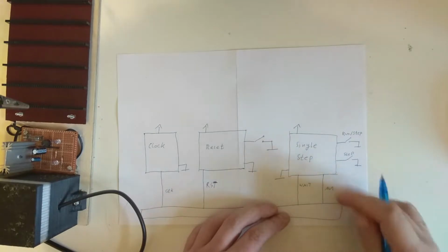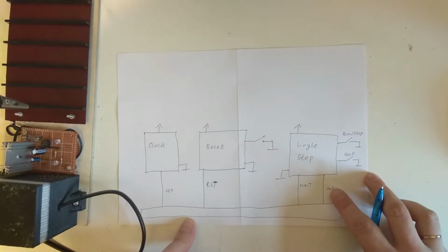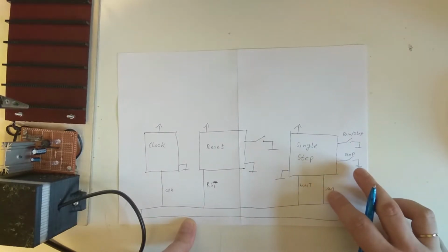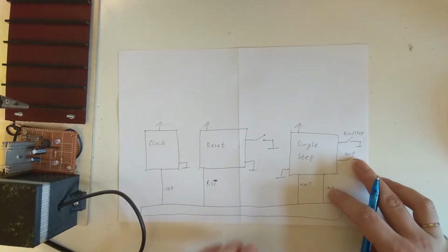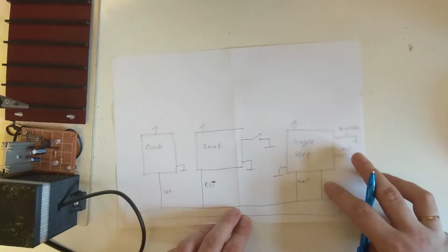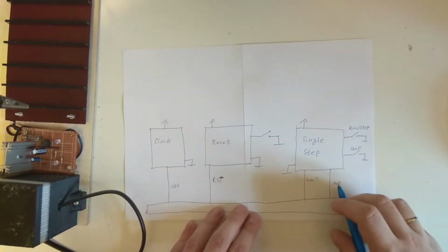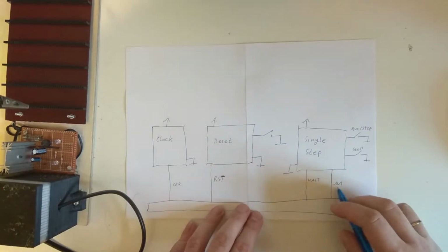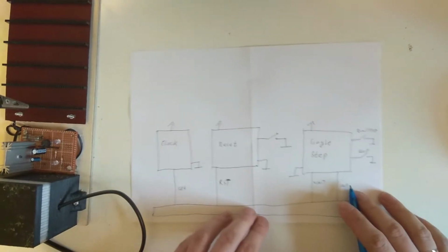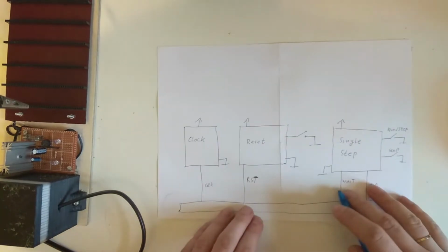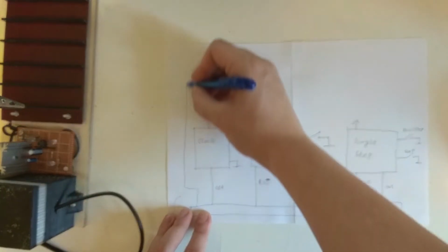And M1 is, I think, machine cycle 1, which is basically something that happens every time the Z80 fetches an instruction. So at the beginning of each cycle, this will go high or low. I don't know what it does exactly, but we'll find out very shortly. And then I'll just draw this as a bus here.